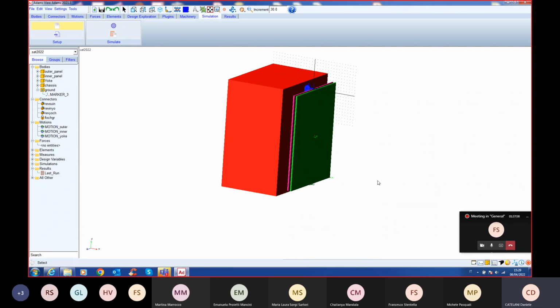From the kinematic analysis, we can evaluate displacement, velocity, acceleration, and the torque in the motion, which will be the real motor, the real actuator to apply this movement. The kinematic behavior will be independent from the inertial characteristics, while reaction forces and actuation torque will be dependent on the inertia characteristics.